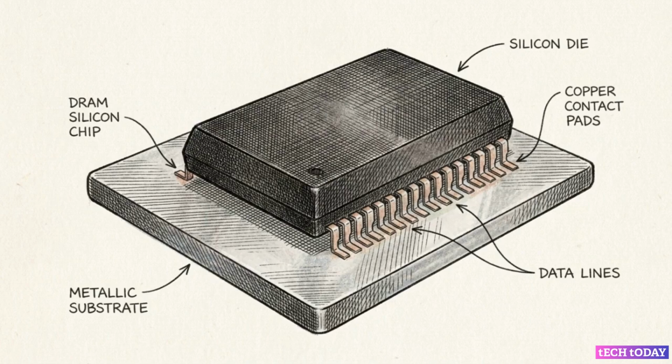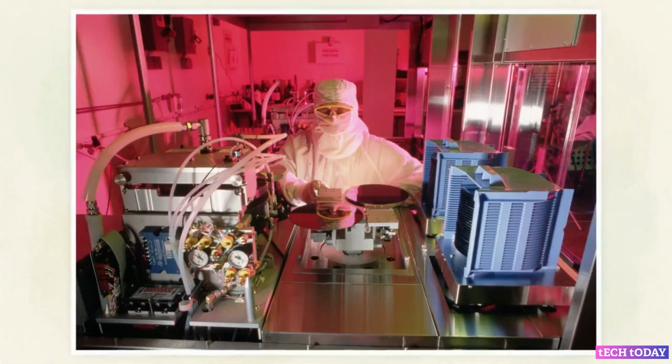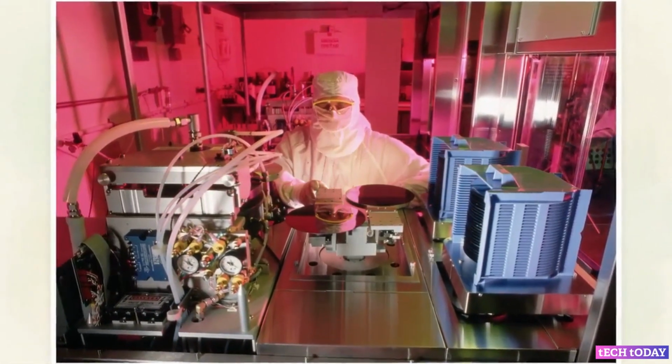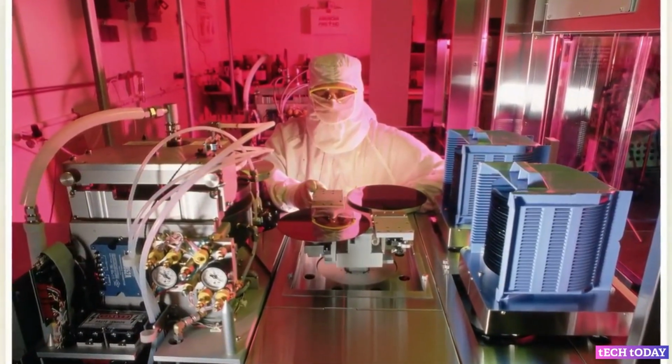These performance targets are limited by the physical electrical characteristics of the DRAM chips themselves. No two chips are identical because of the inherent microscopic variations that occur during semiconductor fabrication. To identify these differences, technicians use electronic die sort to measure these variations, sorting every chip on the wafer into a performance tier.